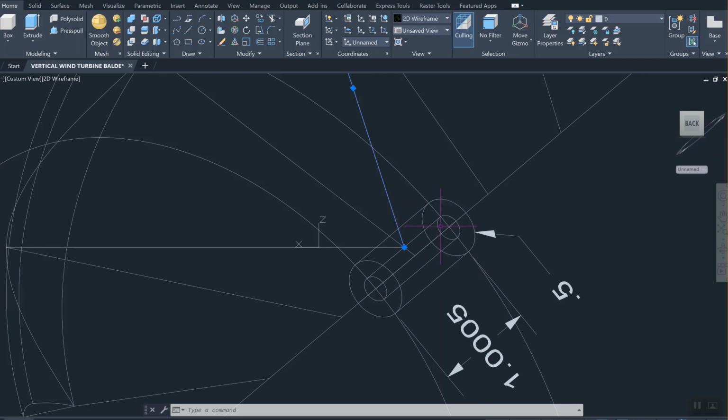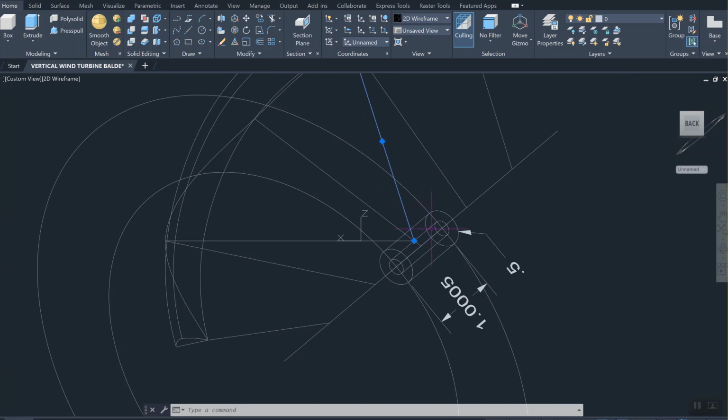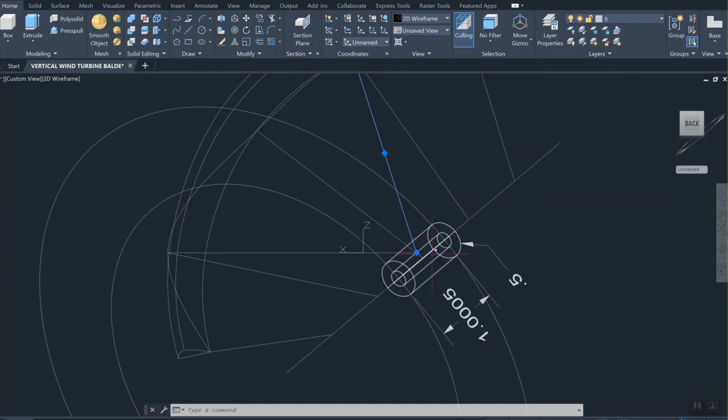All right. And I'm not demonstrating this part. You should be able to do it on your own. This hub part is already created, and it's about 1 inch long and ½ inch diameter, and the inside hole is 0.2 inches. However, we do have two lines created, and I'm going to use one hopefully as an extrusion line or loft line for the support profile.